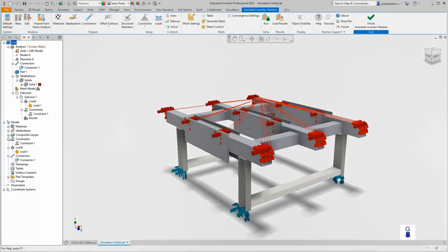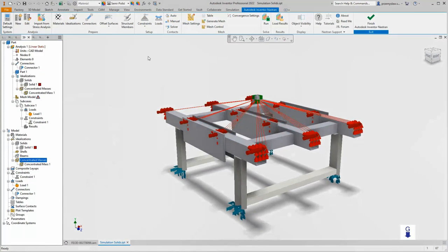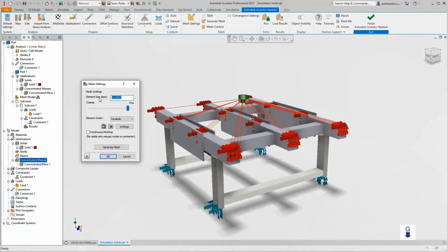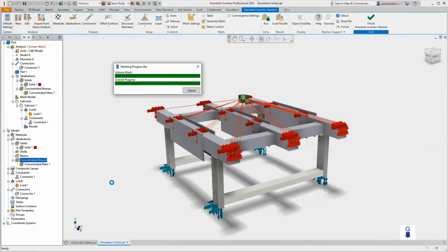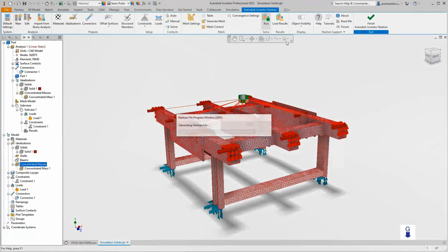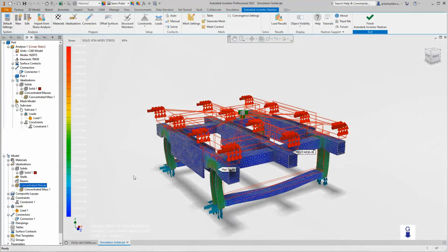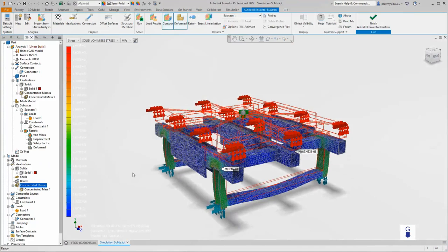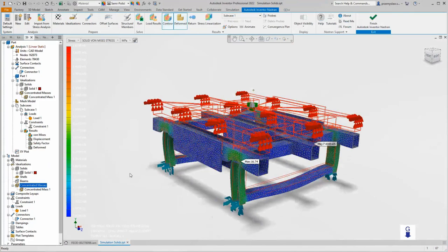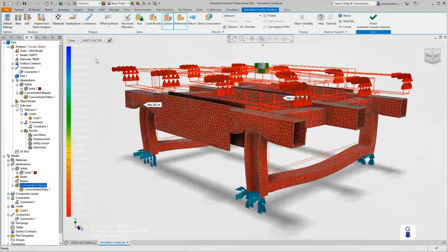And we're not just doing linear studies. We can test your designs for vibration. We can check for the high and the low cycle fatigues. We can see how many loads it can take before cracks begin to form. This is one I really like: we can actually run a thermal heat transfer study, and then we can apply those temperatures to a thermal stress study. We can run a nonlinear study, and these are incredibly powerful and very accurate.